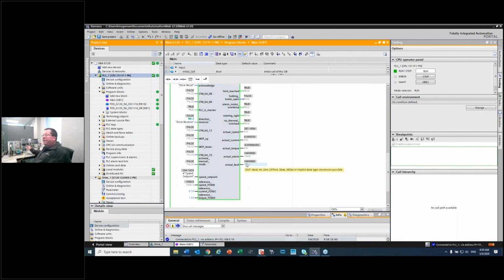So if I give it a little speed, I'll hold the wheel. You'll notice we have an alarm which is saying my motor's getting overloaded right now. And we also have a torque that goes up and a current that goes up. My speed, because it's just volts hertz, is assuming it's still rolling at a little bit more slippage than 508 because of the waveform it sees. But you can see that you're getting feedback with what we're doing with the drive.